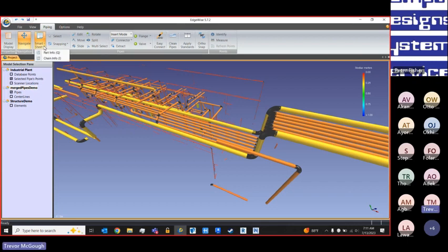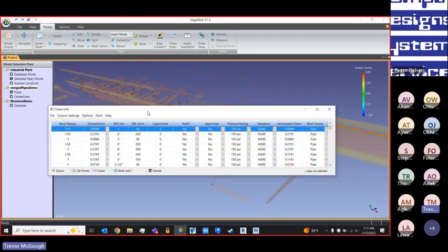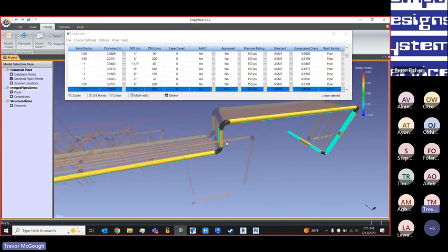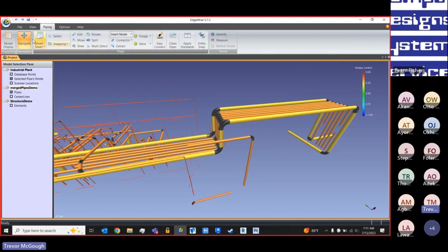The last thing I'll show before we talk a little bit about the export is our second spreadsheet, and that's going to be the chain info spreadsheet. The chain info spreadsheet allows me to manage the intelligence relating to the whole pipe run, including pressure rating and standard information, diameters, and for any of the Revit users out there, we can also control the families. So that way, inside of Revit, we can export as one of 3 different family groups. We could do either pipes, conduit, or circular ducting, and that way it'll come into Revit under that correct family database.